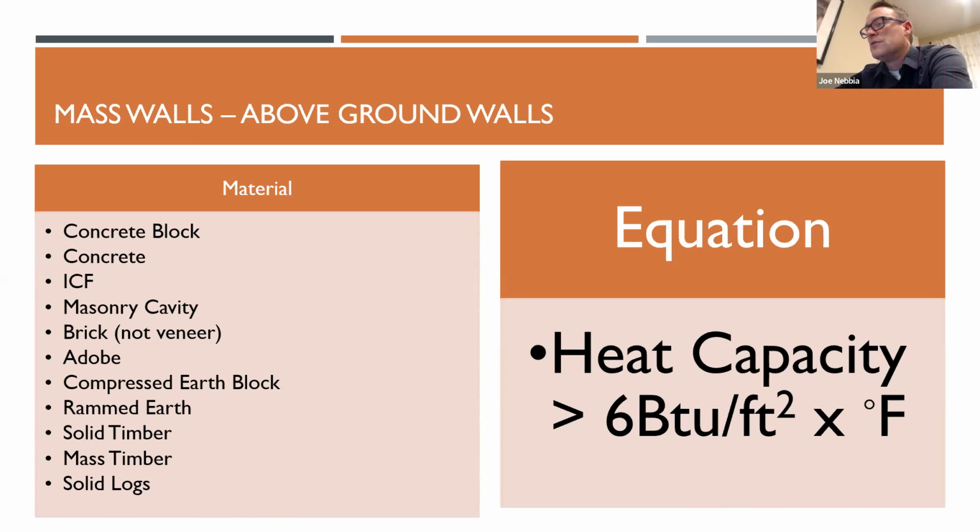There are good reasons to fill the cavity, but you don't always see a cavity filled. One example might be if you're using spray foam, where a certain amount of spray foam can be applied in one layer. And then it sometimes can't be applied. It can be applied again in a second layer, but it's more expensive because you have to come back in and respray. So sometimes for people using a high R value closed cell spray foam, something like that, they might not fill the cavity. Sure.